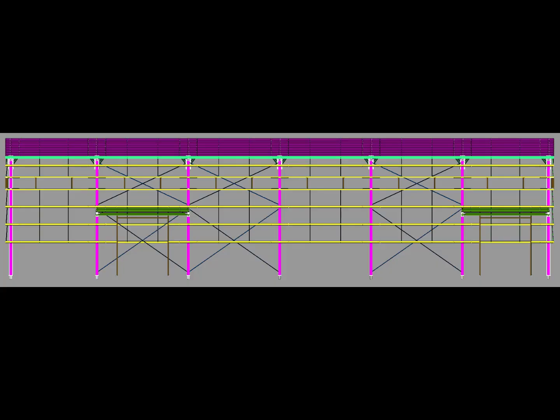So in this slide, instead of looking only at the complete building, we will concentrate on the side wall framing arrangement and understand how the sag rod is positioned within this system. First, look at the overall side wall. The vertical members are the steel columns. Between these columns, we have the horizontal secondary members forming the side wall framing. These horizontal members are important because they support the side wall cladding and transfer the relevant loads back toward the primary steel framing.